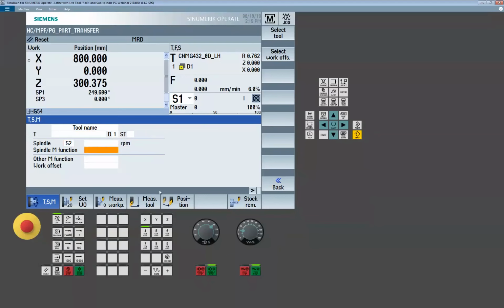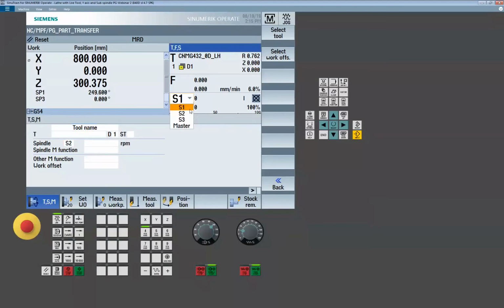Now, is the spindle running? Is it not? So just for real estate purposes, we're not going to show you all the spindles, but if you come up and view the spindle, then I'm going to see the state that that spindle's running in. So here I'm running 500 RPM in a counterclockwise rotation based on my selection. Certainly I could have driven that through G code as well, and we will be here shortly. I just wanted to give you guys a feel of what the multi-spindle environment is going to look like if you haven't had a chance to really get on one and run one yet.